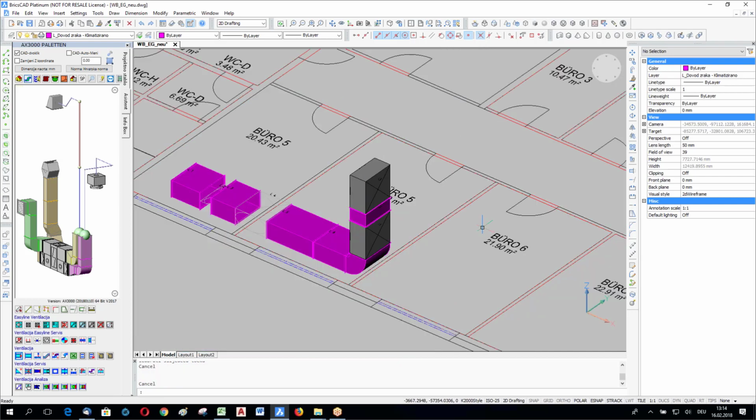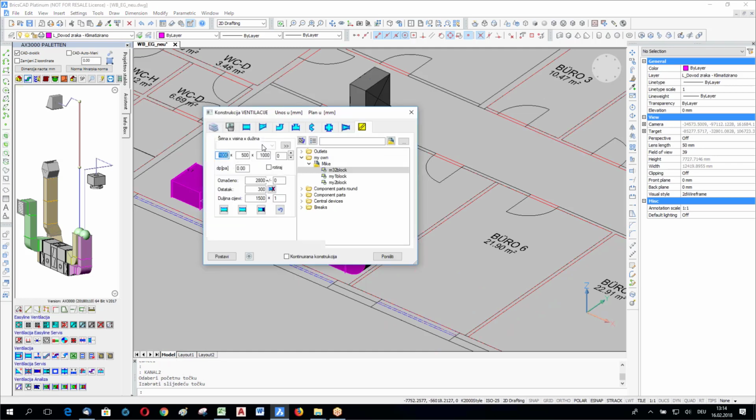If you want to add some tables, size tables, to this type of block, to select here, you need a file inside the same folder. The name could be the name of the block, or it could be the name of the drawing. The software is searching in a hierarchic way for those tables. So in the first step, the software looks for the name of the block, if there is a table available. If not, it's looking for the name of the file, if a table is available. So you can use one table for more than one block if they are inside the drawing at one time.